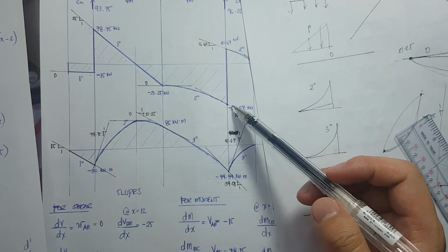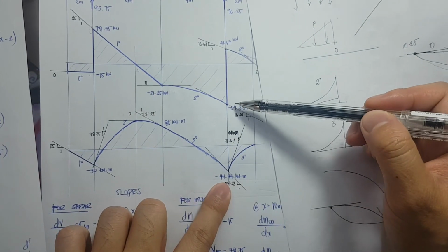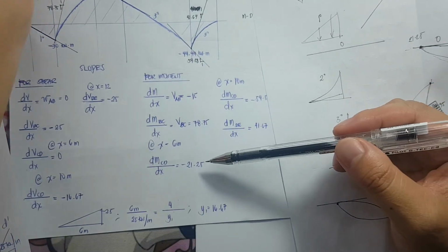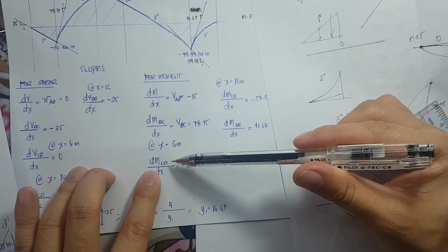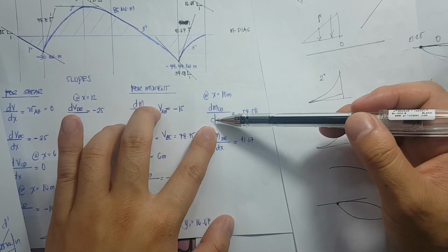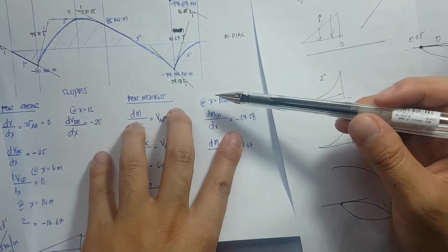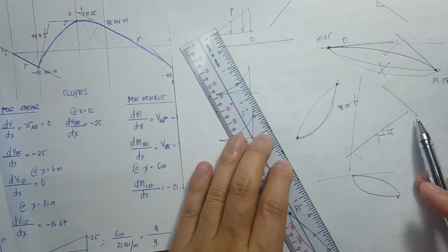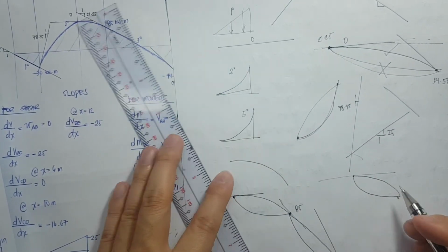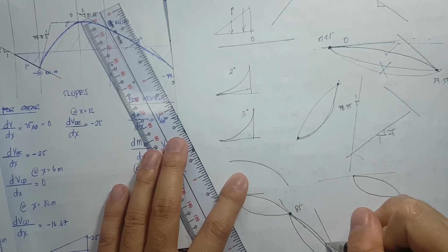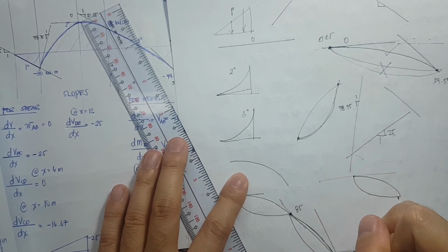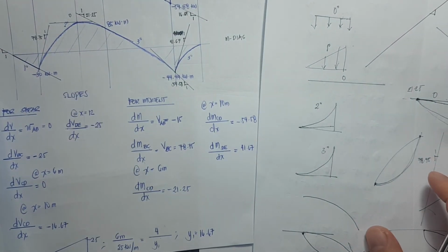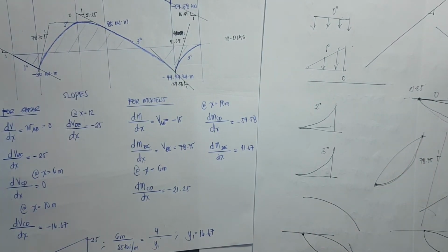What is our slope here? So, the derivative is the load. What is our load there? Or our shear at this point? The derivative of moment CD with respect to dx at 10 meters is negative 54. So, that is negative. Since it is negative, it is sloping downwards. So, therefore, your curve will look like this. This is the curve. And lastly, for segment DE.